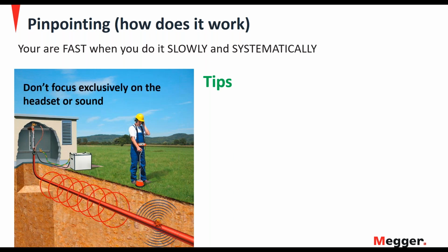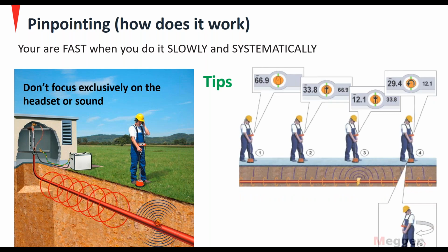What you don't want to do is focus exclusively on the headset or the sound. Yes, it does amplify the sound of the thump. And yes, you can actually pinpoint a fault that way. You can listen your way down to the fault. But we don't want to just listen. The digiphone is giving us much more information than that.